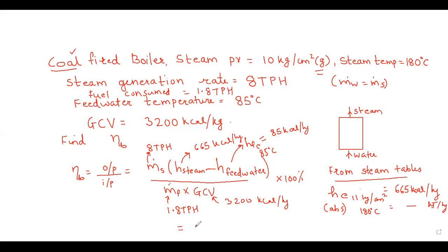Okay, 80%. Let us say that the boiler was rated, from the boiler manufacturer's sheet, at an efficiency of 90%. As an energy auditor, if the rated efficiency was 90%, then you would say that something is wrong with this boiler. The efficiency is fairly low, and you need to do some more rigorous audit and see how we can improve the efficiency of the boiler, because that after all is the job of an energy auditor. So in this lecture we saw how to calculate the boiler efficiency by the direct method.